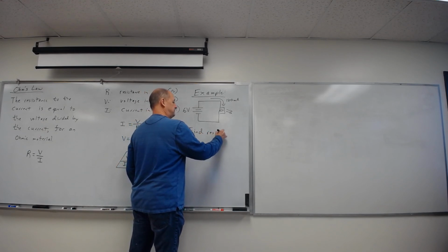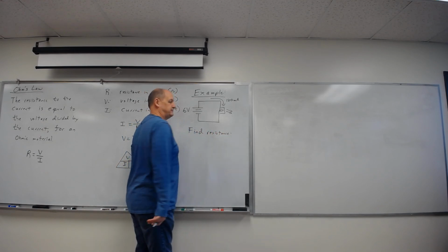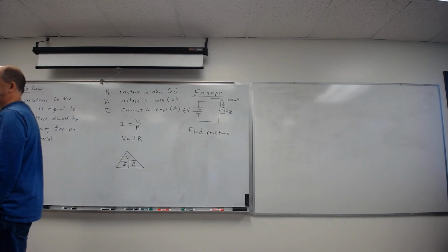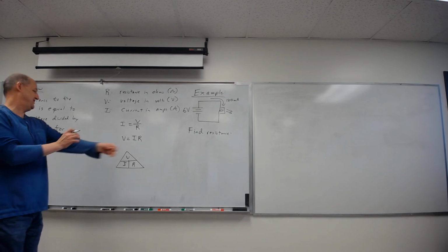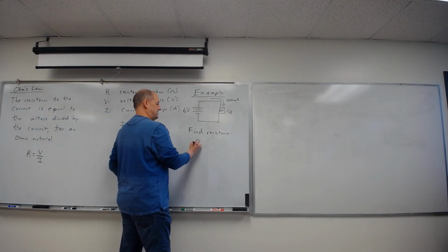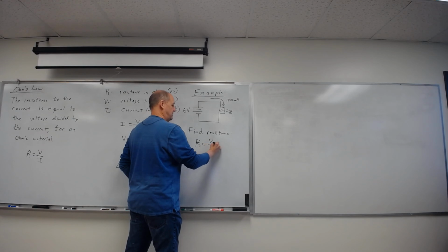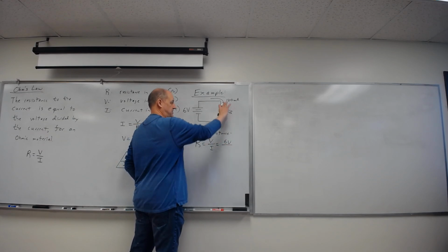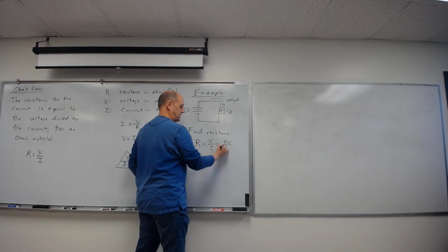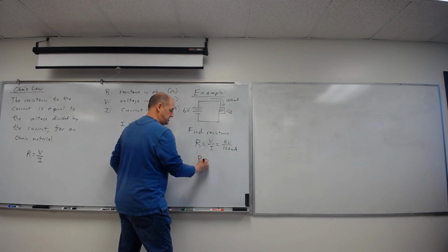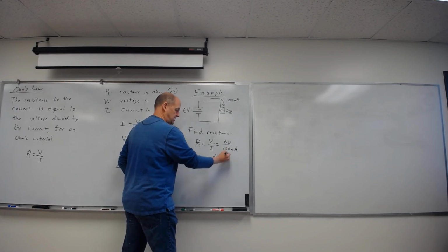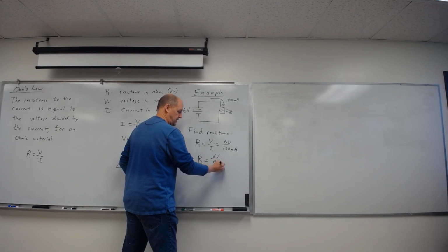Find the resistance of my light bulb. Okay. Technically, light bulbs aren't only materials, but let's ignore that and use our past example to do a calculation with our new equation. Resistance equals voltage over current. Your voltage was 6 volts. You measure from here to here, it'll be the same as here. Your current's 120 milliamps. If I would like to do the calculation, I need that in amps. That'd be 6 volts. Move 1, 2, 3 decimal points. That's 0.12 amps.